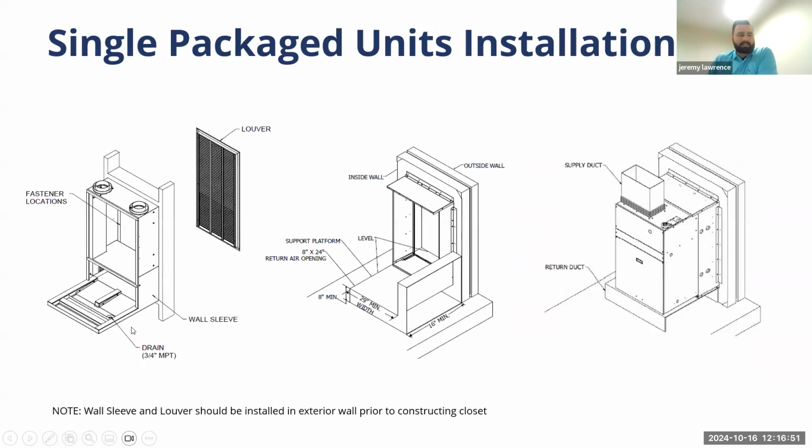So as the building goes up, either if it's a concrete fabricated building or if it's being wood framed, the size of the sleeve is left as an opening in the side of the building. Once the building structure is up, the sleeves are shipped out, and usually the general contractor are the ones that install the sleeves because they need to be secured to the structure of the building and then sealed.